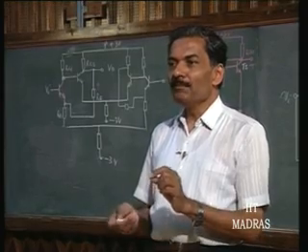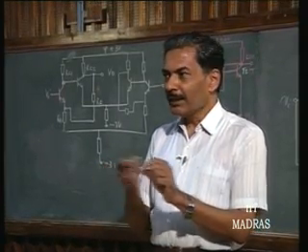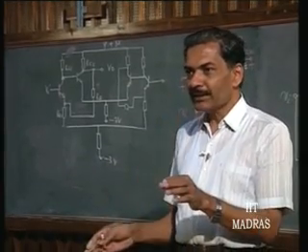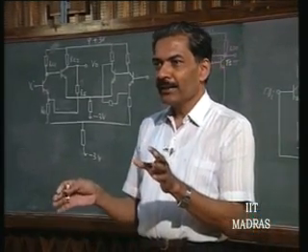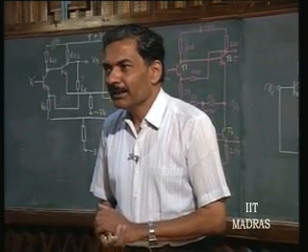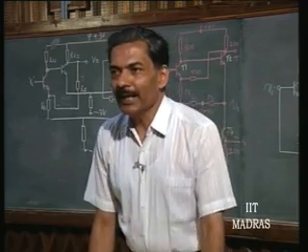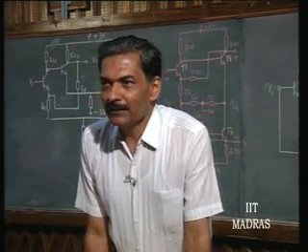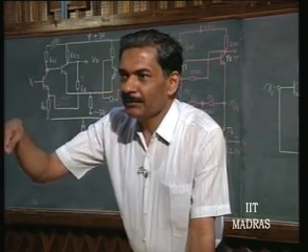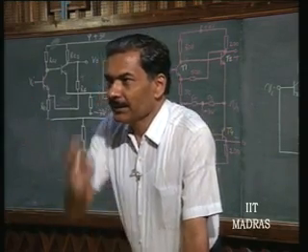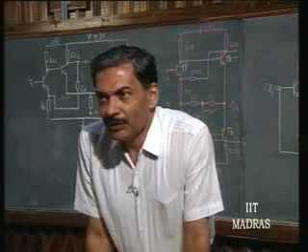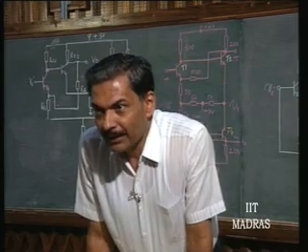What it means is simply increase one of the three time constants so much that the gain reduces drastically within the frequency band, that when the other poles actually come into picture, the gain has already fallen to a value less than 1. So there is no question of the negative feedback turning itself into positive feedback at any particular frequency. This is by drastically cutting down the bandwidth. This technique is not at all suitable for wideband amplifiers with negative feedback.